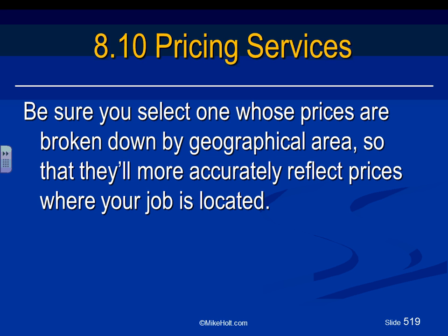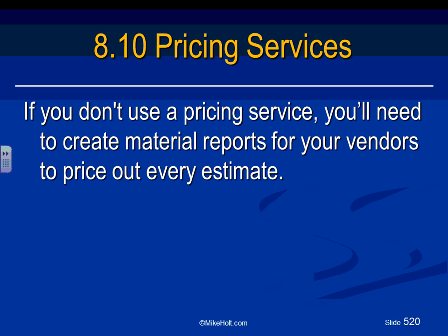So look at this, this is an advice for you guys. When you pick a pricing service, they update the price for you. Make sure they break it down by geographical area. So that's more accurate, because then a geographical area, guys, they will tell you if you're in New York downtown, use price 4. You know what I mean? They'll have 4 or 5 prices, and they will tell you this price 1 is for these areas, price 2 for these areas, and so forth. So then when you're taking off a job in downtown New York or downtown Minneapolis, you could use different prices if you so decided.